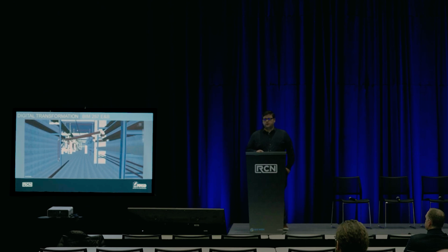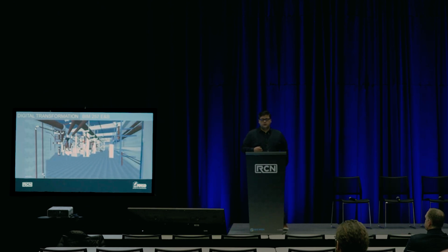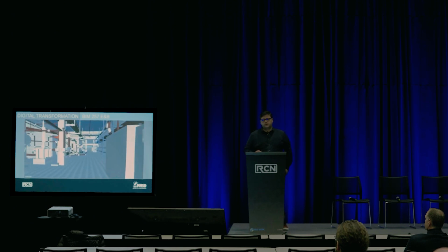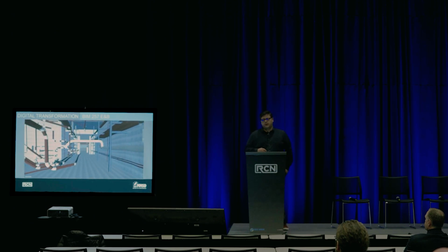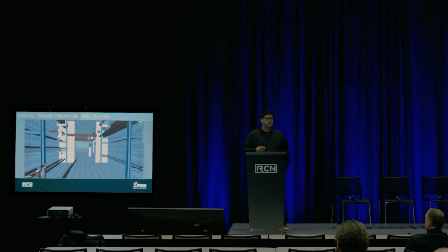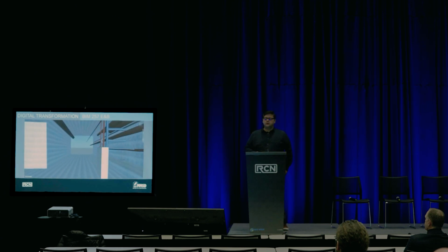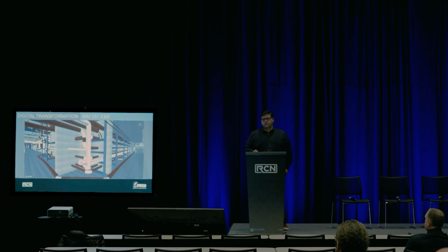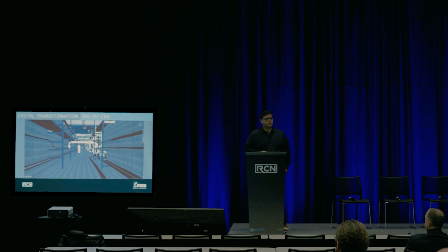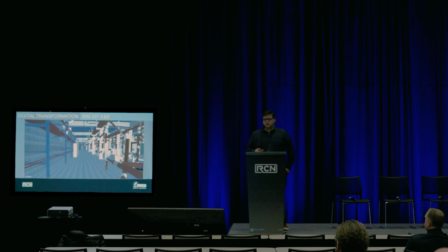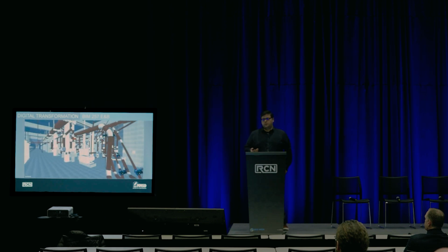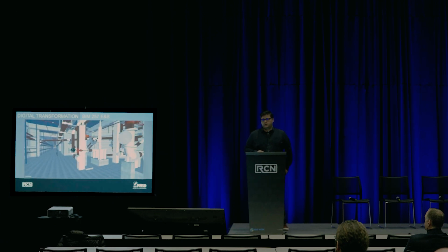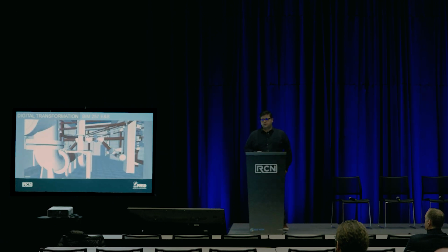Part of the process for creating these BIM models is asset discovery. One of the problems that we ran into on this job, we found 25 assets that did not have a matching equipment ID or asset ID, and they were not tagged in the field or somewhere in the database. So we had to work with both asset management staff and our plant operators to physically go out there and locate these, referencing our construction and record drawings and trying to just figure out which valve was which or which pump was which. And that led to a more complete model as well as an updated and improved database for all of our asset management.